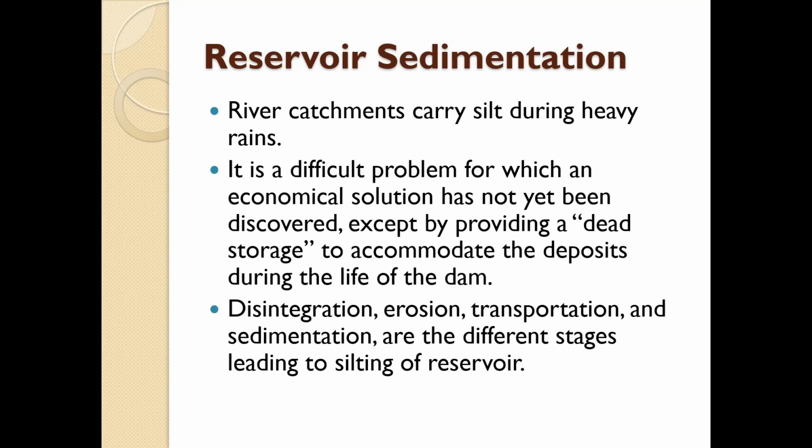Thus, if today at the time of construction a reservoir can store 10,000 cubic meters of water, tomorrow, say after 5 years, it will be able to store only 8,000 cubic meters of water. Therefore, in order to see that capacity does not fall short of requirement during the design period, we must take care of this silt. So basically, it is a difficult problem for which an economical solution has not yet been discovered, except by providing dead storage to accommodate the deposits during the life of the dam.